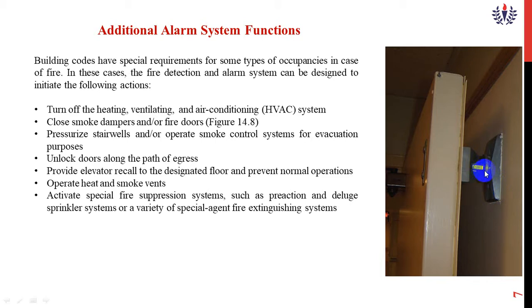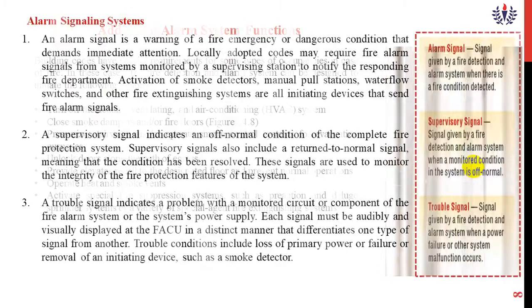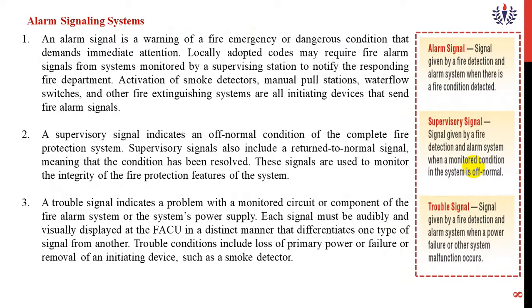Good, good. It is a magnetic door closure. This is designed to stay open during normal building activity and release when the alarms are activated, to close the door. It is one of the magnetic door closure contacts. So when it releases, the alarms are automatically activated. Okay, that is one.